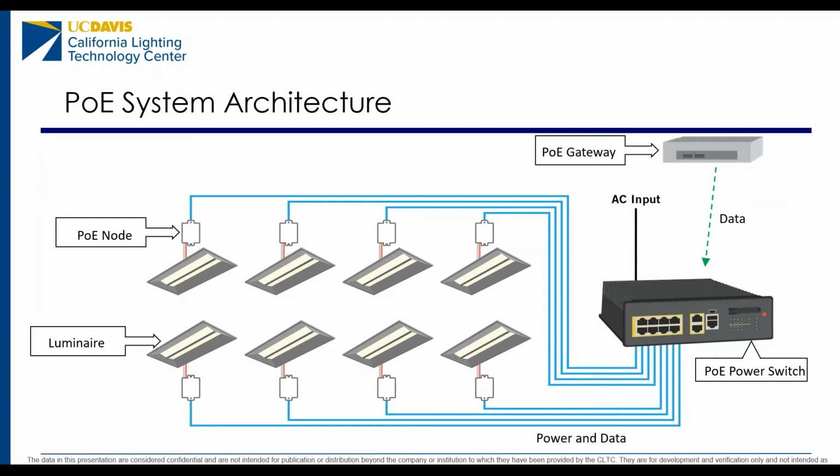And then you have your PoE node, which is basically a communication endpoint, and it provides DC to DC conversion and current regulation to the luminaire. And then finally, you have your luminaire, which is similar to a traditional luminaire, but it's driven by this PoE node instead of an LED driver.